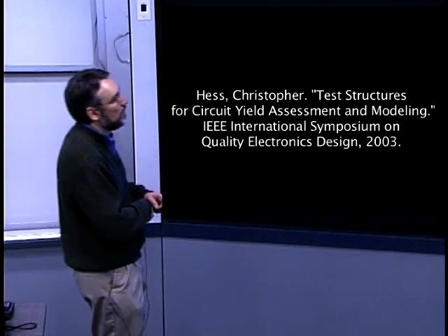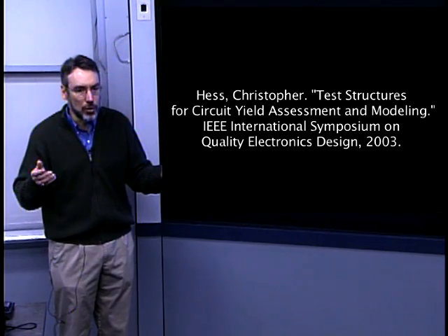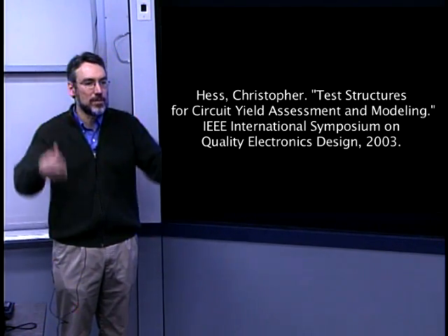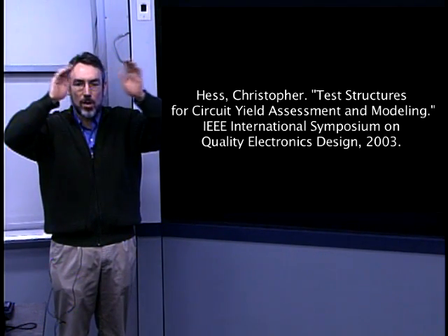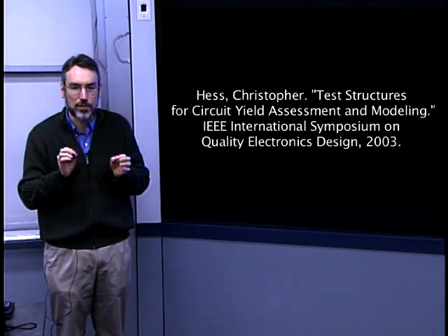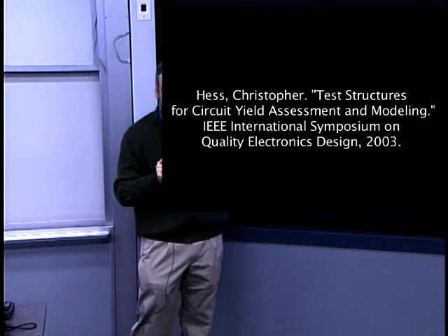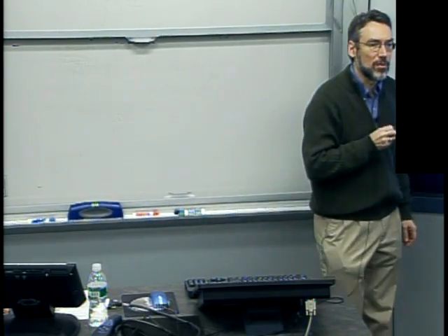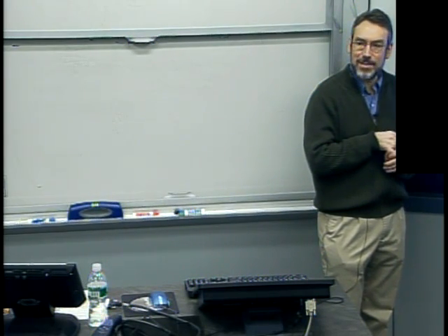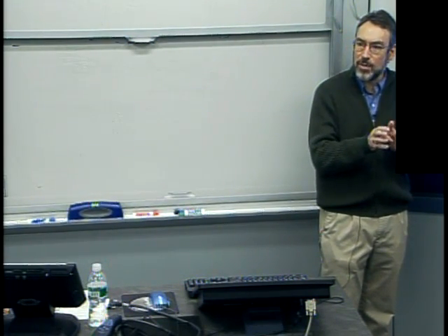And so that's why if you go into an IC fab, it's a clean room, everybody's wearing clean room garments, there's incredible amounts of airflow to filter out and remove all kinds of dust particles or other extraneous matter down to very, very tiny dimensions. That's really the measures that have been taken in order to get the cleanliness you need in order to not eliminate, but get those particles down to a particle density and down to a presence of size that are small enough not to have too big of a yield impact.